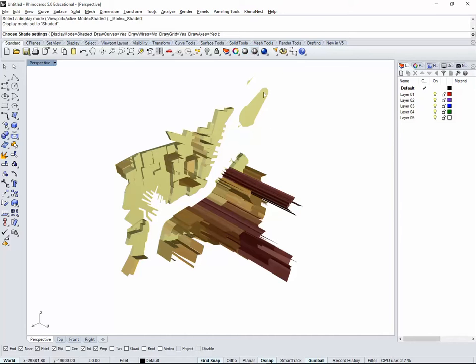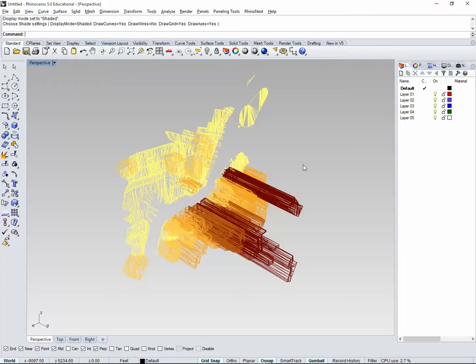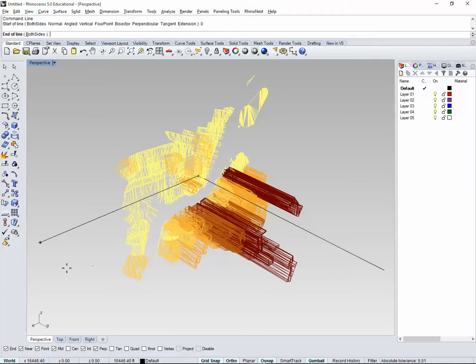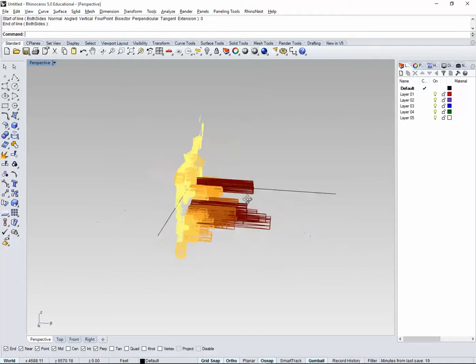So what I'm gonna do is create a line, enter. I'm gonna press 0, enter, so it starts from the 0 exactly. I'm gonna press Shift, or you can go to Ortho to create a very large orthographic line. And I'm gonna do another line, enter, and I press 0, enter, to create another reference line.